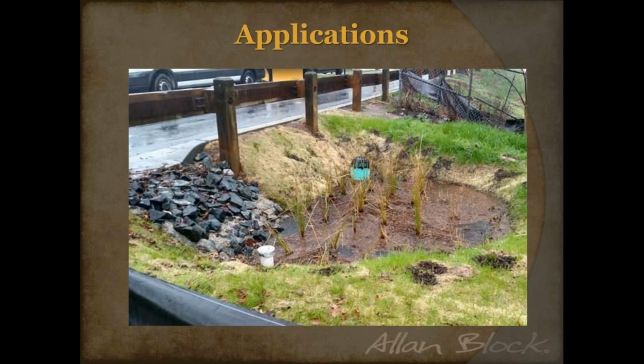So here's a couple of applications I just grabbed from different manuals or different websites that I saw, and here's a great one where you can see you've got some type of a paved surface, and that water is going to be introduced, and it's going over some rocks to take out some of the major garbage, but also slow that water down so you can minimize erosion. But then it's being introduced into your pond. And so now you've got your soil media, you've got your vegetation, and you've obviously got your monitoring points and your overflow. So you've got those elements associated with that bioretention pond.